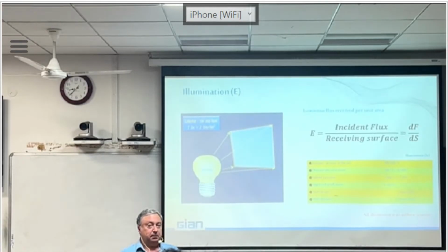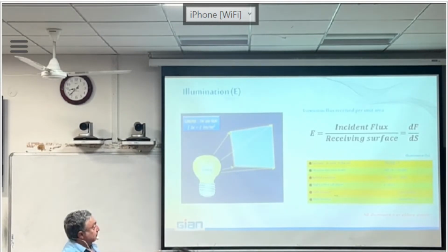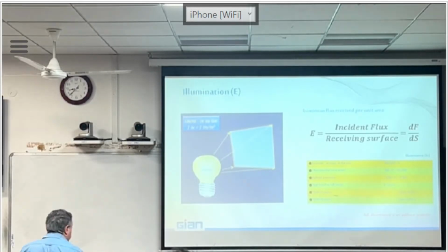In fact, we need a lot of light when we have a huge space. When we reduce the volume, we can reduce the light. And this is a good point. Otherwise, for 400 lux here, I have a few kilowatts of installed power; imagine that we have to multiply that by 100 at least in order to achieve 100,000 lux, the same quantity of light.